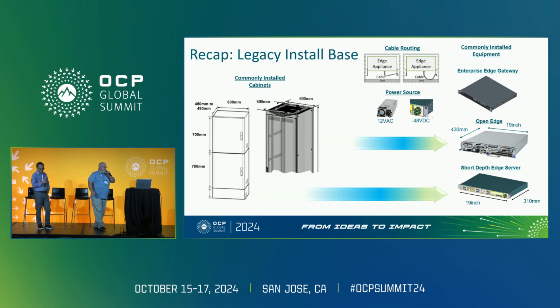That forces solutions, shown on the right-hand side, to be implemented where you're dealing with about 300 to 310 millimeters to allow yourself to cool solutions and get airflow through them. And that gives you a little extra room at the back and the front for cable routing and the ability to get air out the back to recirculate it through the solution.